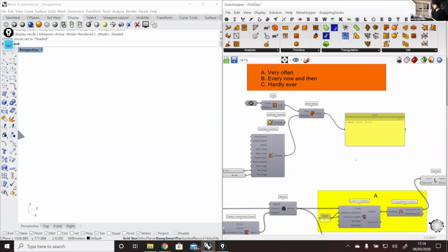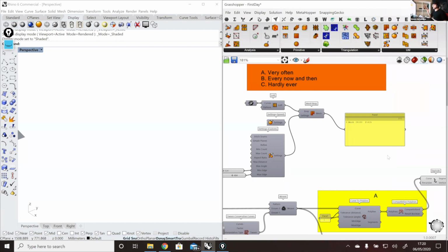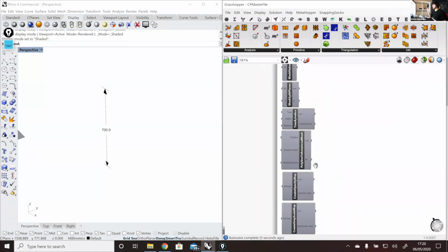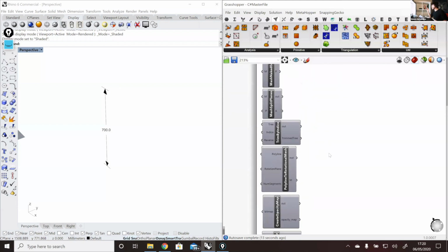However, it has a bit of a problem, because if the plane is exactly in the same position as a vertex, then it can kind of break the final solution. But if you can use this splitting of meshes by a plane, it's very optimal. We also have a C# component that extends this solution, because we had to operate on a mesh in one of our projects and used this splitting a lot. So we extended the solution that Grasshopper has, and we actually have a C# script that splits a mesh with a list of planes. So this is like our bucket of C# scripts.